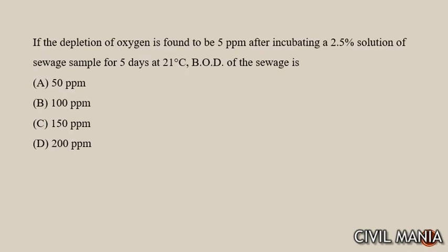नेक्स्ट क्वेश्चन है, if the depletion of oxygen is found to be 5 ppm after incubating a 2.5% solution of sewage sample for 5 days at 21 degree, what will be the BOD of the sewage? The BOD of the sewage will be 200 ppm.